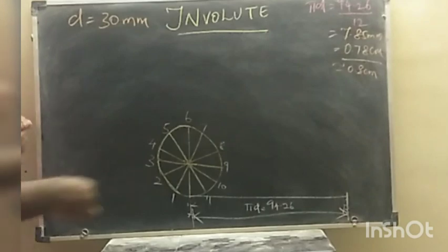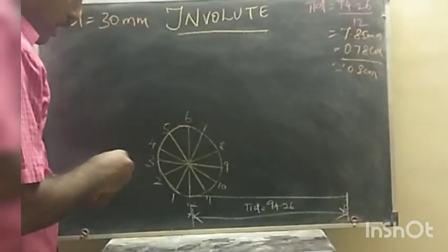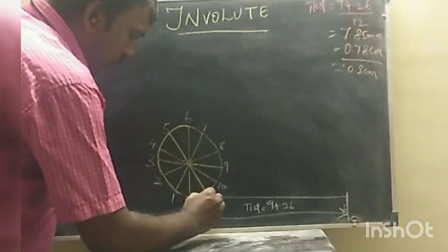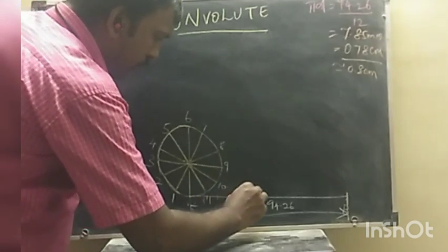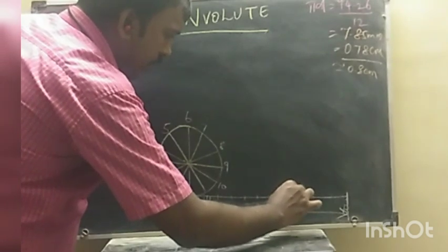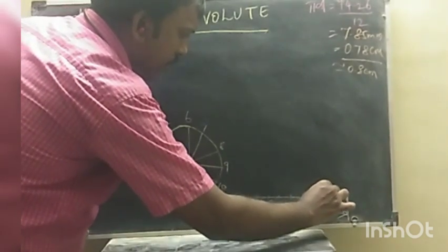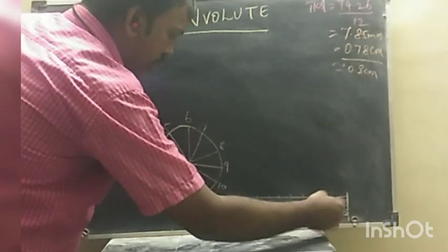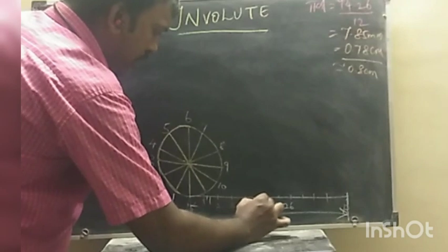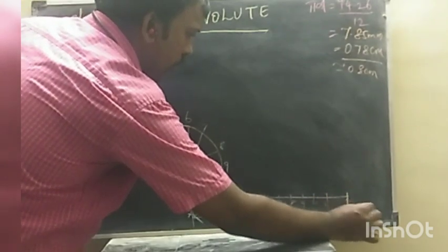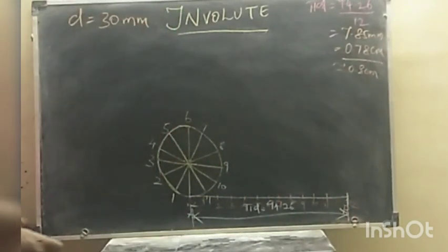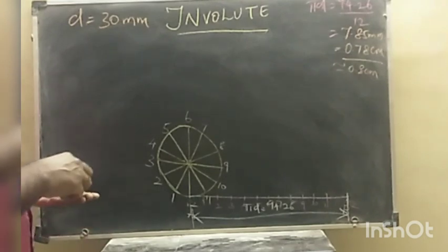So right now what I am going to do is I will take point 8 and divide these line segments here. So if I divide, this is the first point, 1, 2, 3, 4, 5, 6, 7, 8, 9, 10, this is 11 and let it be the 12th point. Here you may get a little bit smaller than this. Anyway I am giving the namings, and due to little space issues I am drawing in this manner. Now I have captured all the divisions. The next step I need to draw a tangential line from each and every point.